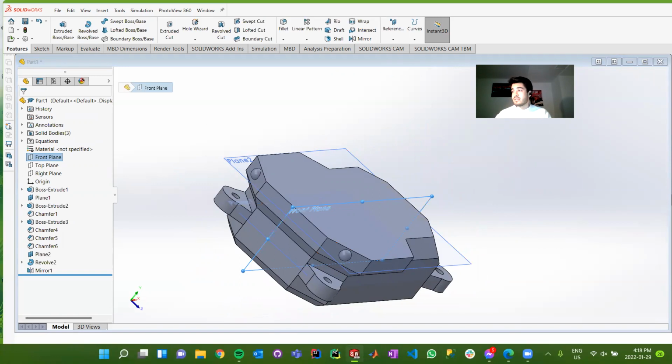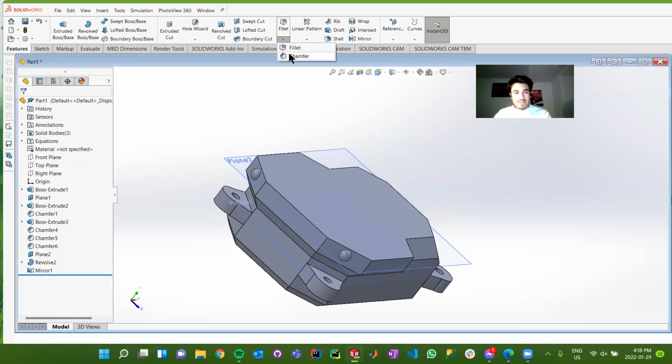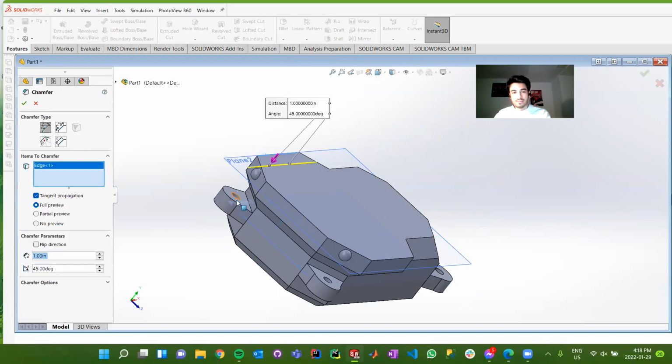So what I did is, in the past, I made a 0.5-inch chamfer with a 74-degree chamfer angle. So I'll show you what I mean. So this top edge is looking a little bit peculiar. So what we can do is click chamfer. And then from there, just give it a moment. Oh, sorry. It opened up on my other monitor. My apologies. There we go. Let's click chamfer. Cool.